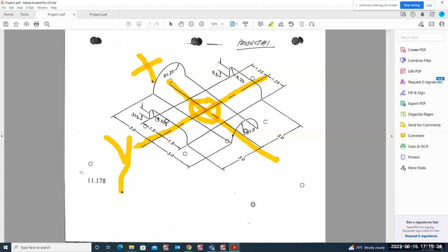In the right side plane, if I'm going to create this arc right here, that's going to be a z positive, right hand rule. Z positive, how much? From here to here, if you look from the origin, your z is going to be positive 3 inches. If I'm going to create this arc back here in the construction plane right, that is z minus 3 inches. So I'm going to start with construction plane right, and I'm going to create this arc right here, 1 inch radius arc. And here is my z.